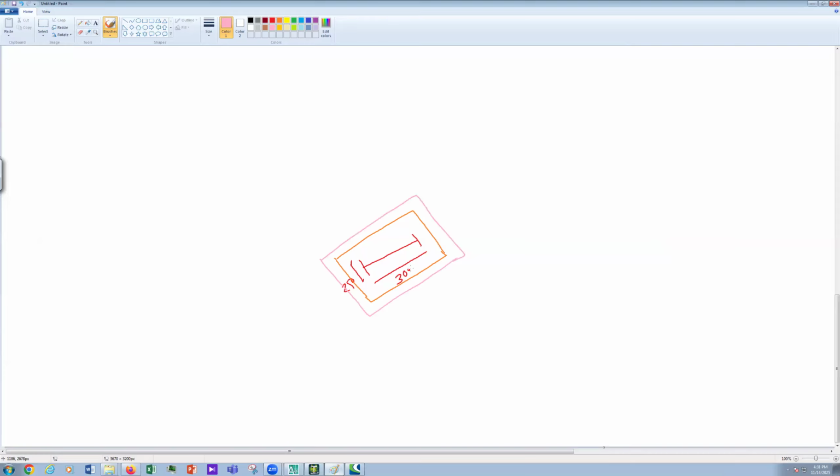If you have 300 here, then from your column, your base plate is 75, and from the base plate, your steel column outline is 75. So 75, 75, 150. Here is the same, 75 and 75, so here is 150 total.